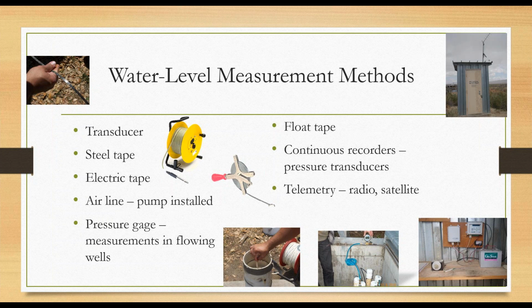There are pros and cons, problems with steel tapes though. If they do kink, they can really impact your measurement. There's a higher cost associated with a steel tape. And this diagram right here is the steel tape. Also, it's possible that they can hang up in a well. So if you're not careful, if you don't have a weight at the bottom in a deeper well or even a shallow well, you want to make sure that tape does not stick to the side of the well and give you a false reading.